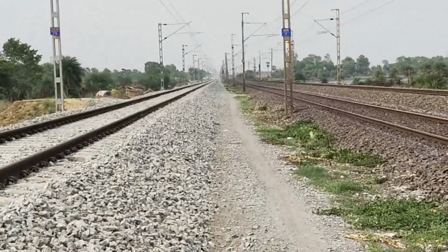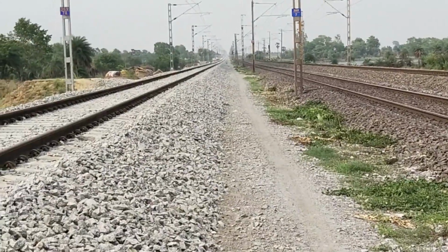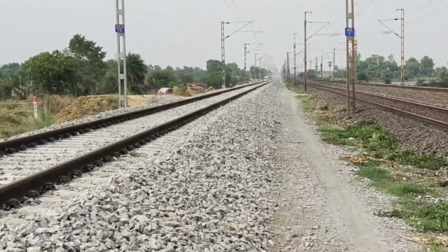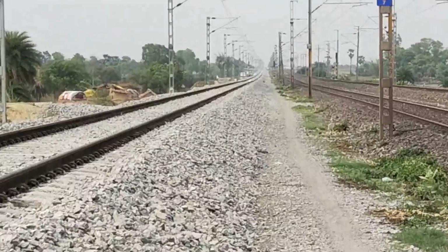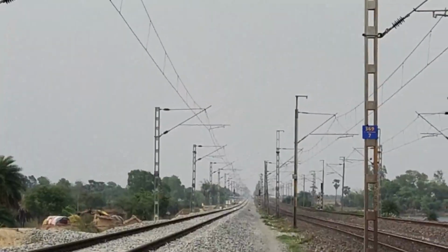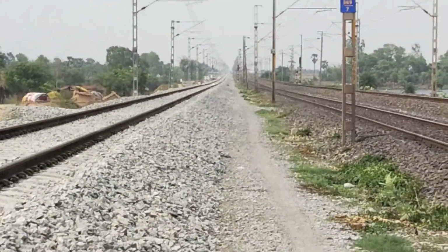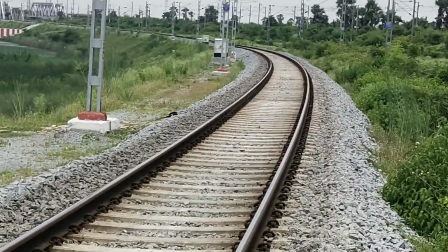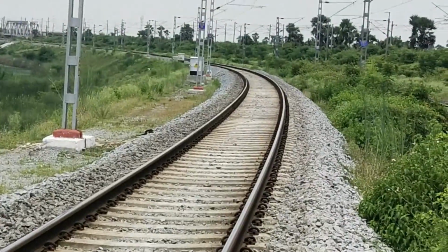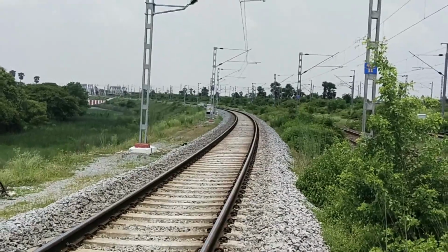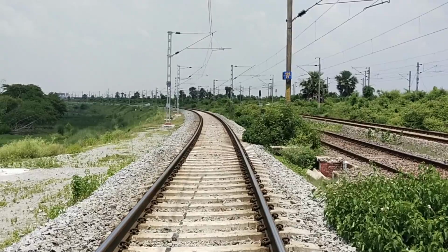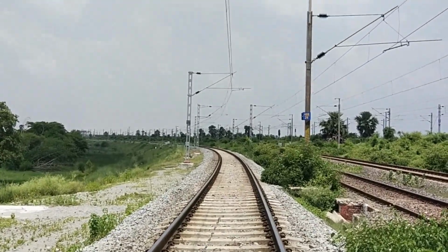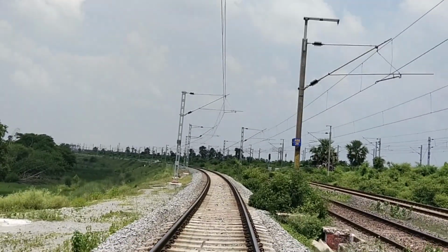In horizontal curves, vertical curves of summit type shall be avoided, especially where LWR is also there. In LWR, the track will have a tendency to lift up on such summit curves, and due to horizontal curves, there are lateral forces as well as a tendency for offloading of vehicles.